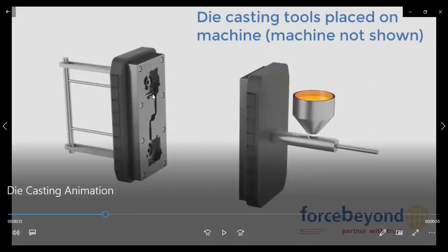You see, that's the mold cavity that I was talking about. To be able to fabricate this mold requires a lot of research and development and therefore cost, right? So that is where this molten metal will flow and sit. Once you have applied that pressure on the plunger, that molten metal will be forced to take the shape, this hollow shape. It will go and sit there.